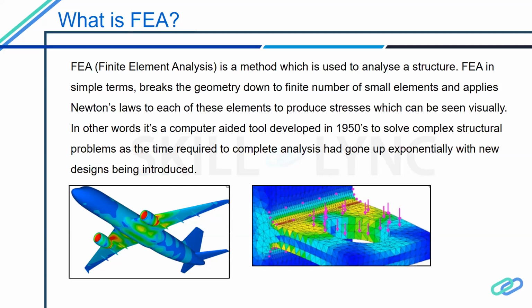If you want to do flow analysis, they use computational fluid dynamics, which is a finite volume method, to analyze all the flow problems. And also a finite difference method, using an explicit solver like LS-DYNA and Abaqus to solve all the dynamic and crash problems.